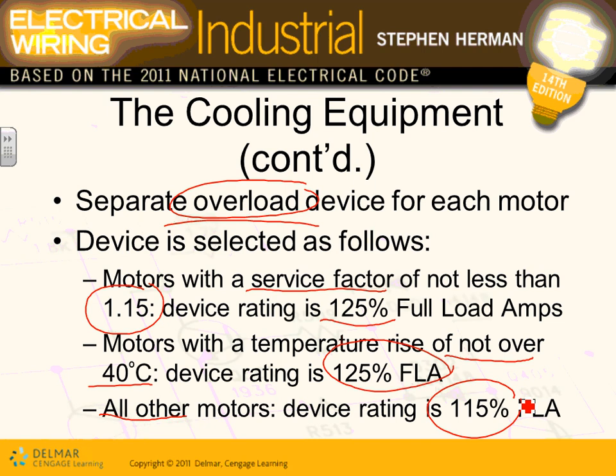That's how you size the overload protection for a chiller or a motor or anything else, exactly like we did it in our test. But you multiply by the nameplate, not the NEC code book value. You multiply by full load amps for the motor. Nameplate value. So that's basically what we do with that.